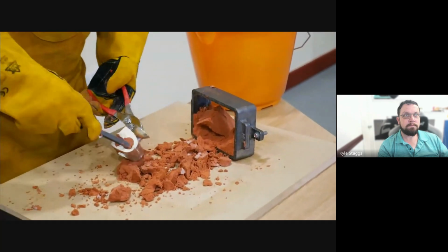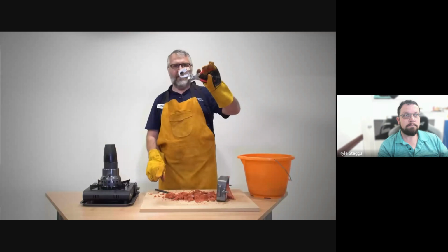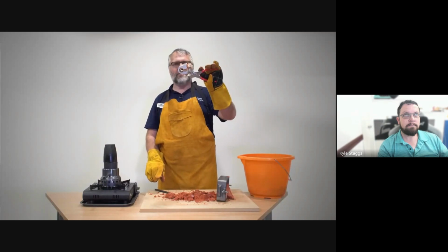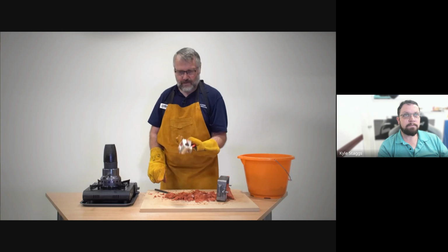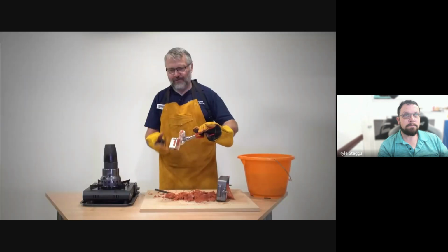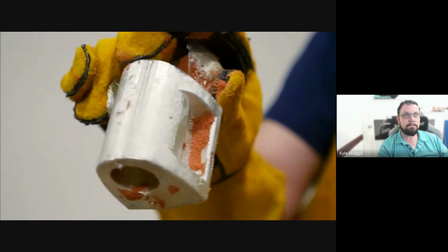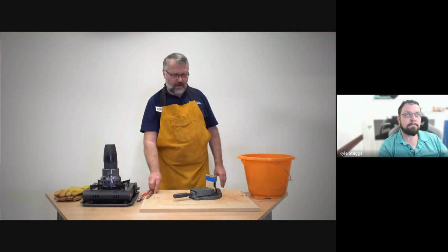And then we can just take the sand from the core, just poke that out, and there we have the hole right through the casting, and it's come out quite nicely aligned on the joints. We just have to cut the sprue off, and that can be remelted for the next job. There's very little waste in the foundry industry. So now we're going to look at die casting.